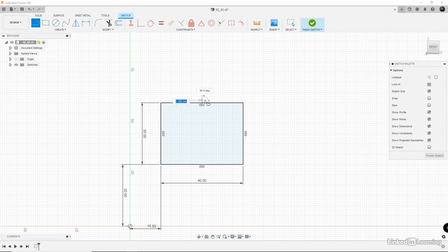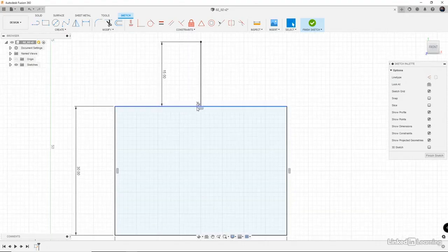So let's select that, and then we come up and you can see we can create, like normal, any angle and length. But when we come all the way here to 90 degrees, you can see that it also creates a 90-degree icon right there. And that is the 90-degree or perpendicular icon. And let's select a distance of 15, hit enter. And now you can see that we both have a midpoint and perpendicular constraint applied to this line right here.